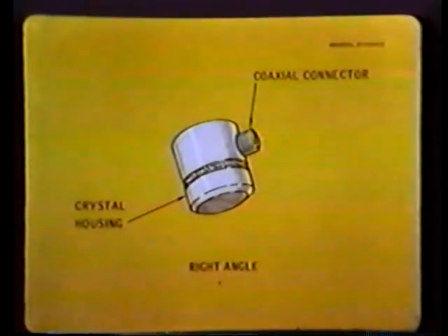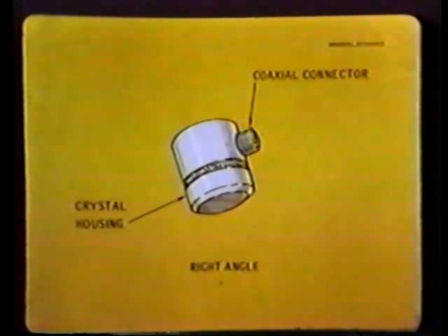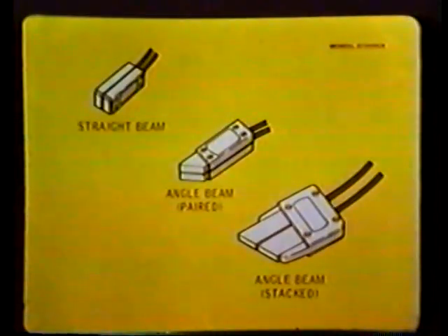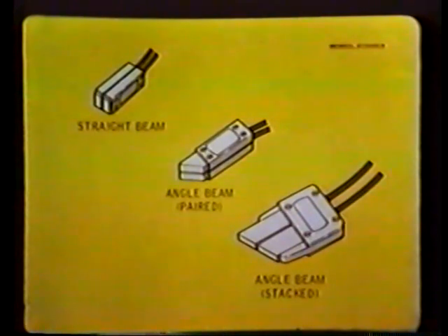Till now, we've discussed transducers mostly in the singular sense, either as a transmitter, a receiver, or a single transducer used as both a transmitter and receiver. There are also double transducers, two single transducers mounted in the same holder for pitch and catch testing.